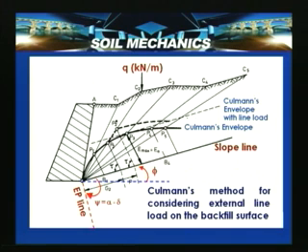So as discussed in the previous lecture, Culmann's method can be used for determining active or passive earth pressure thrust, and basically this is a graphical method. So what we need to do is first represent the wall to a scale and the ground surface, and any surface like in this slide, where you have got a range of surfaces like AC1 and C1 to C2 with another slope C2 to C3 and C3 to C4 and C4 to C5.